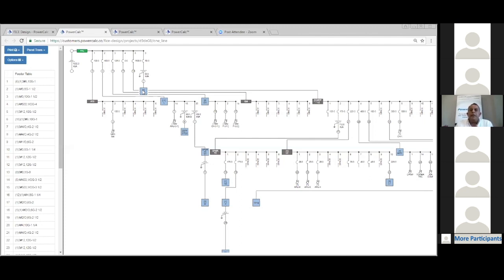Amperage interrupting capacity is based on if everything goes haywire, whether it's on the panel or close by the panel, that extra energy that is going to pass through this panel towards the fault is a tremendous amount of energy. So the panel has to be designed, in terms of the bolts and how it's all constructed, to sustain that much power and energy going through it during a fault.